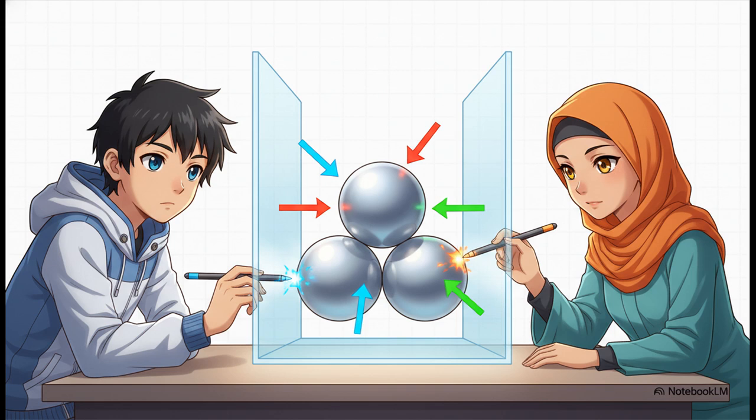Sum your vertical forces to 0 to find the normal reactions, then take those known forces, apply them to cylinders A and B down below, sum your X and Y forces to 0, and you'll find the wall and floor reactions. It's literally just a step-by-step puzzle.